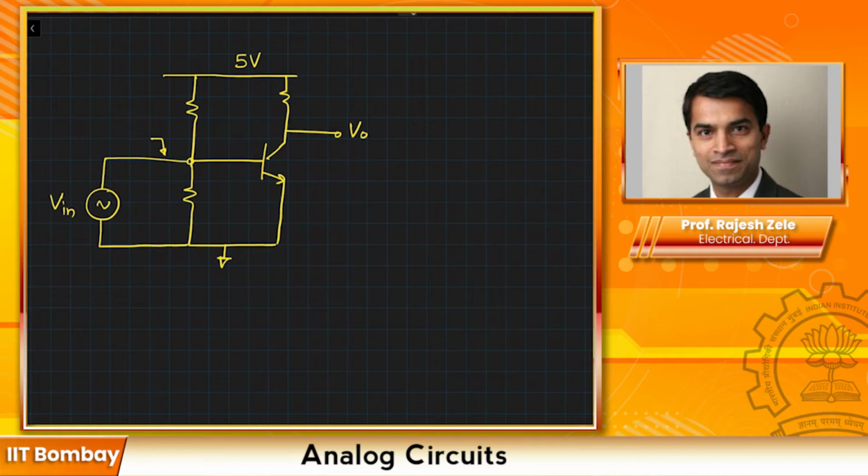So typically you would like to see a DC voltage source in series over here. This would be your DC biasing, VDC input, and this VDC input has to be the same as our original operating point, which is equal to 0.7 volts.